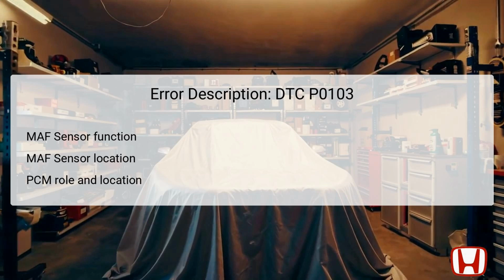In the Honda Pilot, the MAF sensor is typically located in the air intake duct, positioned between the air filter and the throttle body. A high voltage condition, indicated by DTC P0103, suggests that something is malfunctioning within the sensor circuit, usually due to wiring issues or a faulty sensor itself.